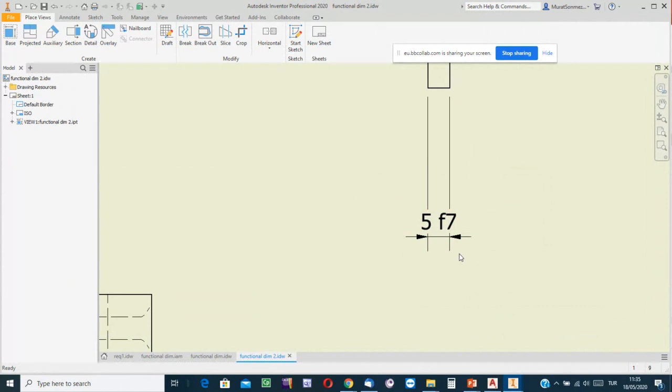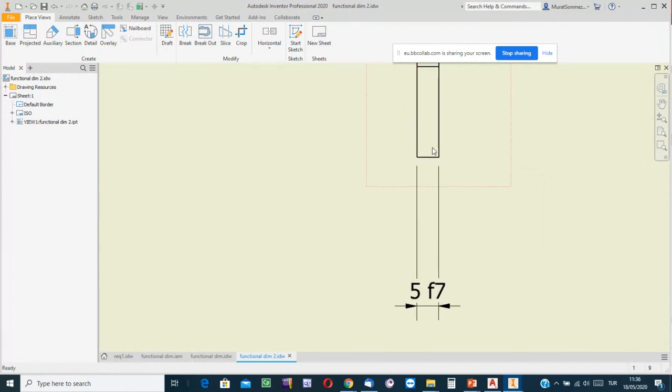Technicians and operators applying the cutting process need to set the size of this part in the range that corresponds to this tolerance grade, F7. After manufacturing, when we measure the thickness of this part, if the measured thickness is less than or equal to the upper limit, or greater than or equal to the lower limit corresponding to F7, then we can say that it is okay. It has been manufactured sufficiently correct in size.